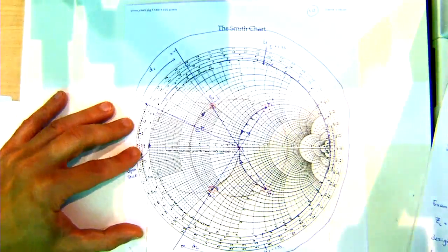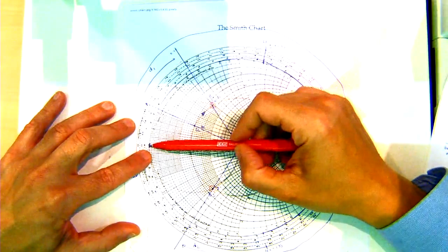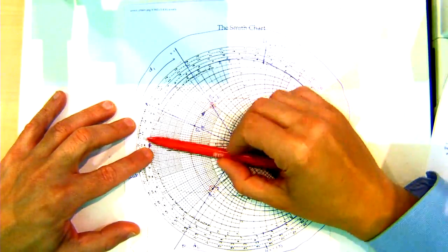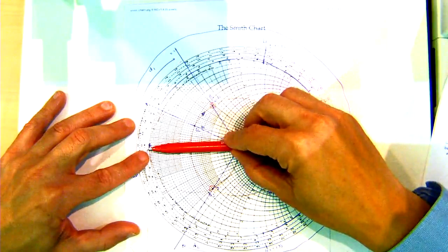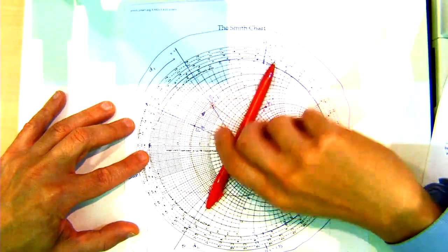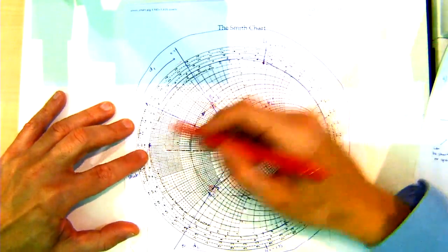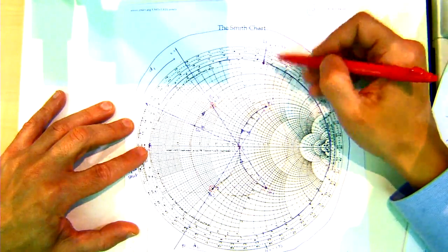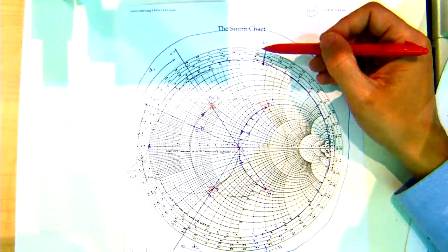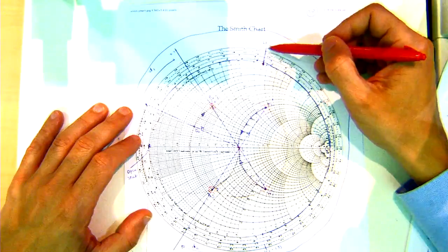Okay, so we know this is the admittance of 0, and essentially what we do is we travel, depending on the length, on the Smith chart, right? So we want to get to positive 1.33, that point. Since we started from 0 and this is the length, you just read it off, and it's, I don't know, I'm a bit blind, 0.4 something, 0.47, 0.48. So that's probably 0.147 is probably the right value.